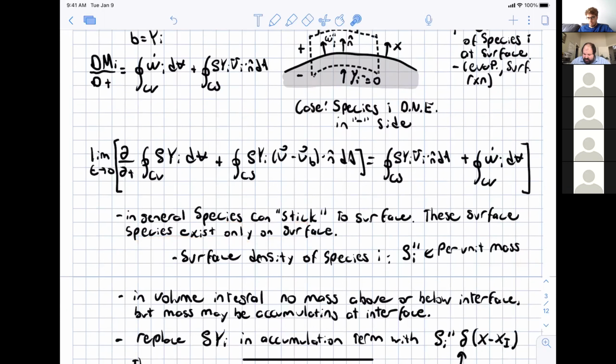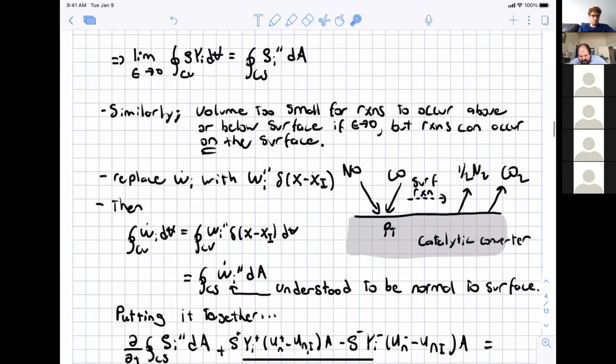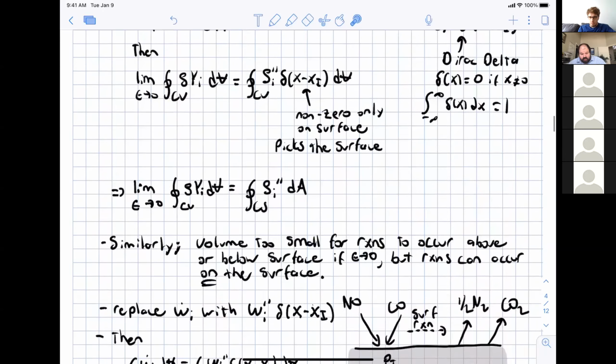But if you work in engines or, say, gas turbines for power generation, and you're working on after treatment of the combustion products, you may have to worry about surface reactions. Basically here, when the nitric oxide stuck to the surface, there is a separate species, the surface concentration of NO on the surface. And that's called a surface species.